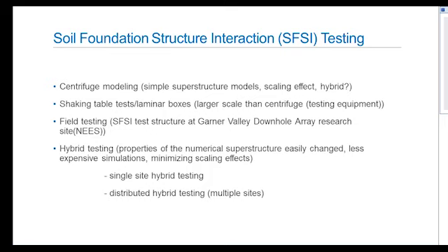Further, the majority of hybrid tests are really single-site hybrid tests, but there is maybe a resurgence of distributed hybrid testing, which is beneficial to soil structure interaction problems because the size is important there, and limitations of the actual lab facility are overcome by using multiple sites and testing, let's say, the structure at one location, foundation at another location, or partition the structure and test it at different facilities.